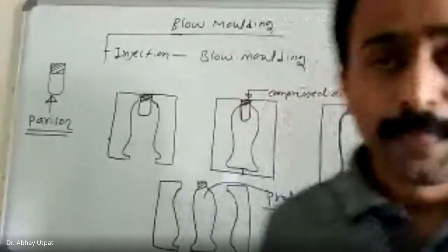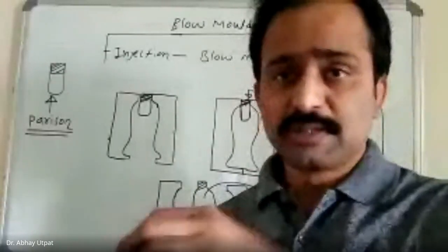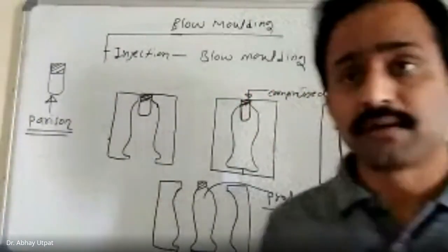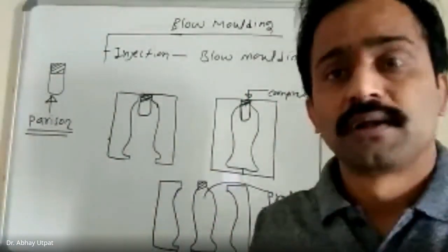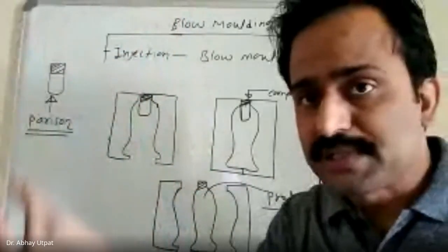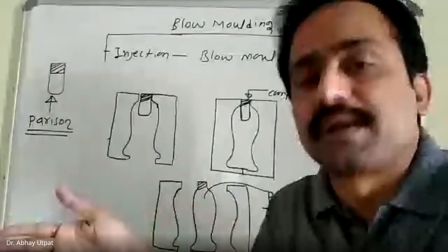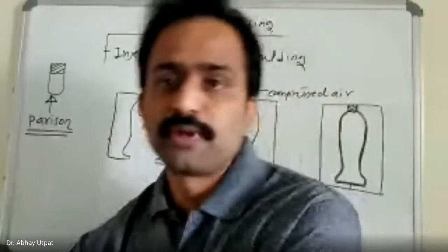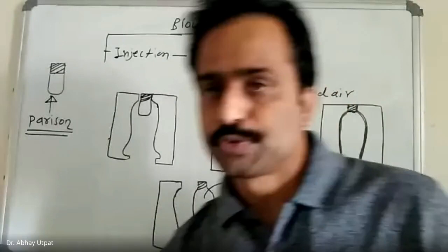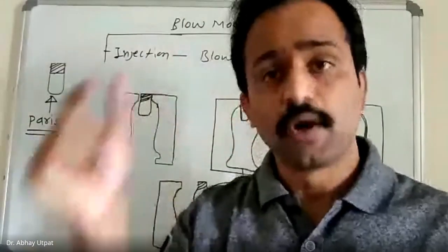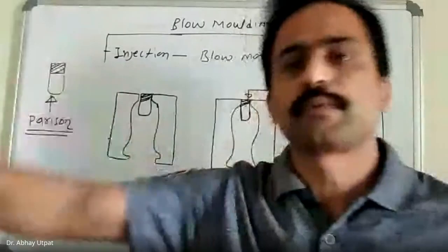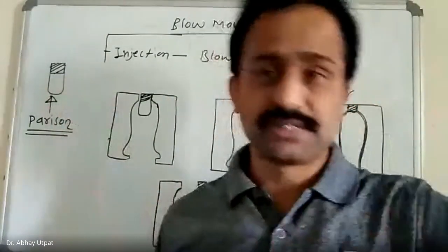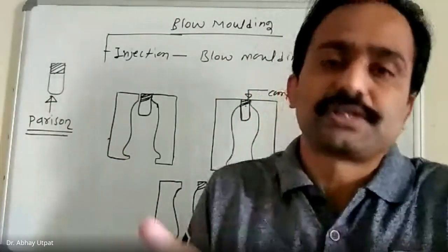How? Now, this plastic usually may not be easily extruded, that's why it is used. Now, this is not like extrusion molding, where directly hot pipe is coming and it is easy for swelling. But here, this is now raw material taken from a bin. Thousands of products are kept in one bin. Then the operator takes it and fits one manually, or with the help of machines, one component is automatically adjusted into the dies. In that case, hot compressed air is used because you require a little more pressure for swelling.